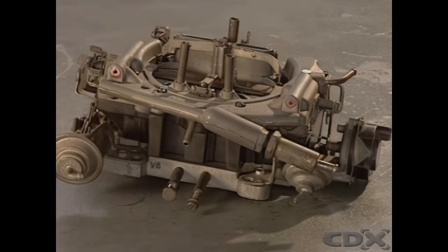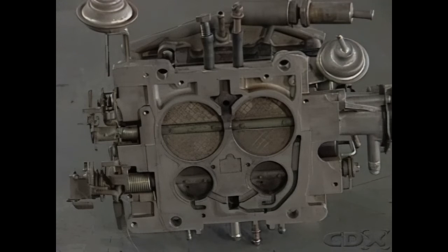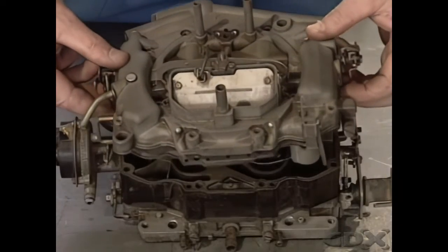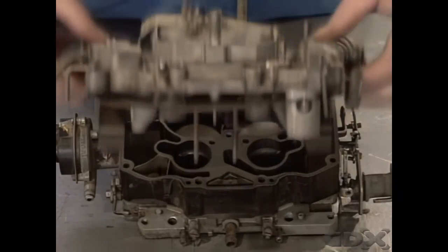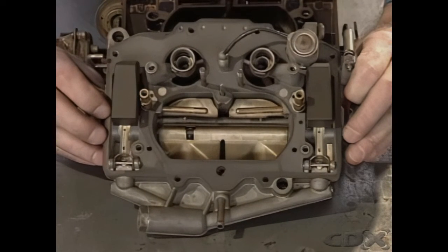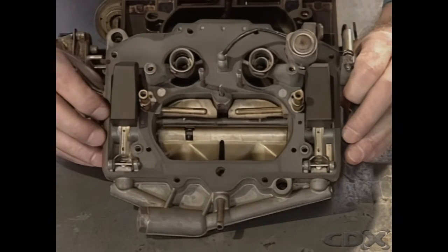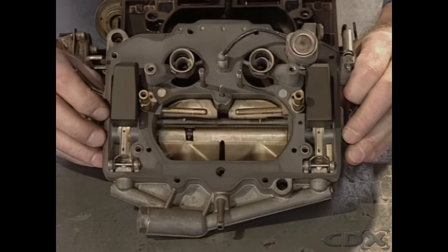Large capacity V8 engines may use a 4-barrel carburetor of two-stage design, effectively two-stage carburetors combined, with each side supplying 4 of the 8 cylinders. A central moulded plastic fuel bowl and suspended metering system can be incorporated into the design. This gives lower fuel temperatures with more precise fuel metering and closer control over air-fuel ratios.